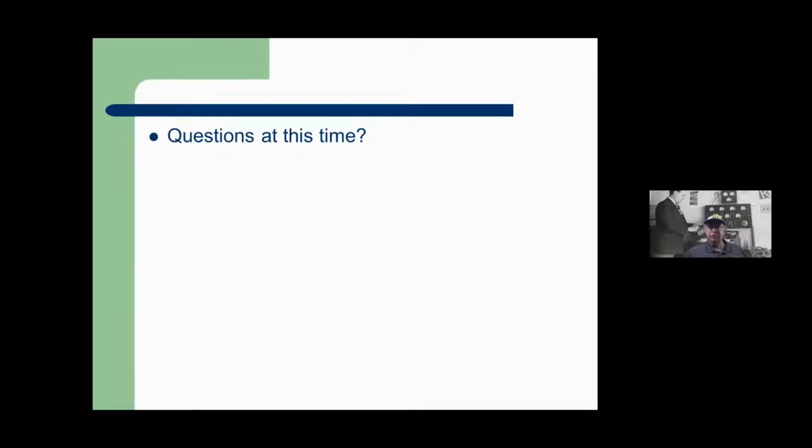I got a question from the chat. Where on your website are the rankings? Okay, they're sorted top to bottom by close-in dynamic range or phase noise limited, whichever is lower, so it's always worst case. If you just look at the right-hand column, it starts at 110 for the new Yaesu, and it goes down to numbers in the 40s.